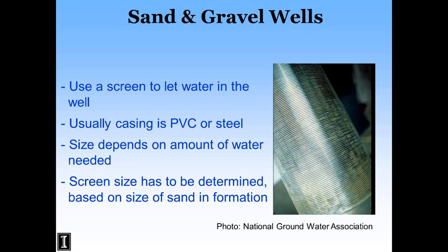Okay, so sand and gravel wells. Here's a well screen, and so the way that works is there's tiny slots in the screen. It's woven, kind of like a screen on your door, but much smaller openings so that water can pass through, but the sand that's in the formation can't.